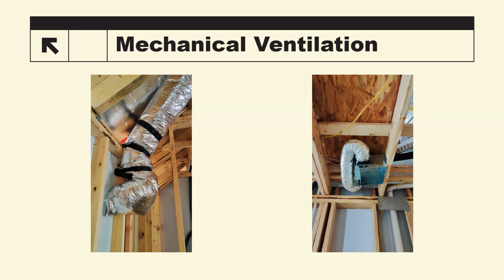And then, of course, some common sense reasons for failure, again, is compromised ductwork. We talked about that earlier: if you see a duct that looks like that on the left, it's not going to have the best chance to pass. And now in 2021 and beyond, with mechanical ventilation being required to be tested, you're just setting this up for failure. So I know the one on the left is coming out of the attic. It exits the ceiling. It comes down the outside wall. A chase now has to be built to enclose the duct. However, the duct is already compromised, and 9 times out of 10, when they build this chase, they're going to be told to build the smallest one that they can, which means they're probably going to crush this ductwork. This really shouldn't be allowed to be done that way, but it does happen a lot.